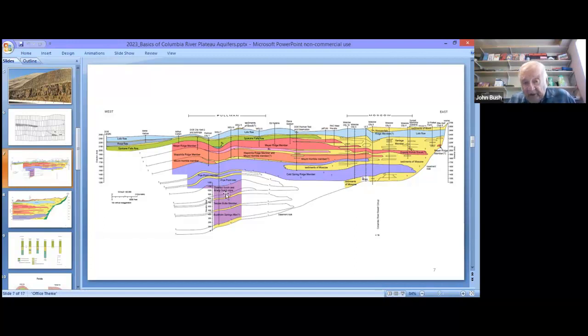He uses the term that these aquifer systems, or these aquifer units in the subsurface below what's now called the R2, were not nearly as prolific as those in the upper. And since most of it is interconnected to the upper anyways, drilling that deep to get the water doesn't mean we have new resources down there. It's interconnected to our top aquifer. And the cost of drilling down that deep is expensive.